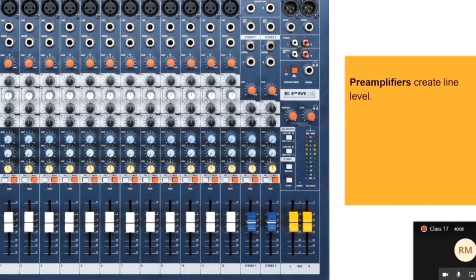The first thing that happens on all mixing boards on Earth is that these round circles with the three holes, or these quarter-inch phono inputs, are the gateways to a device called a preamplifier. A preamplifier converts microphone and instrument level into line level. Preamplifiers beget line level. Now we're in business. Now we've got a nice robust signal that, though it's not going to start a fire like speaker level, is strong enough that it's not corruptible.